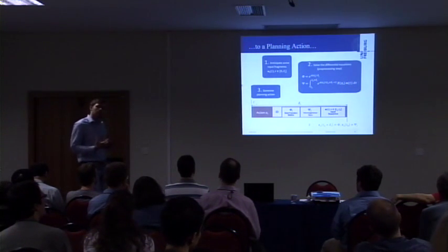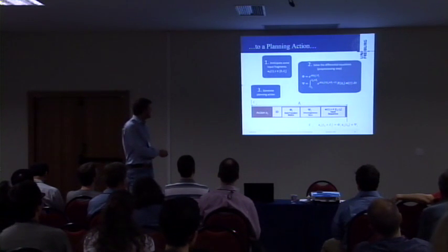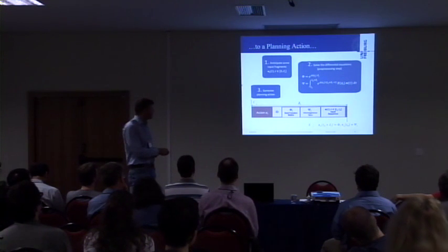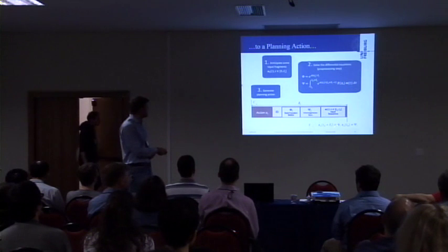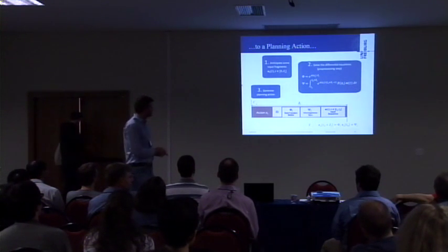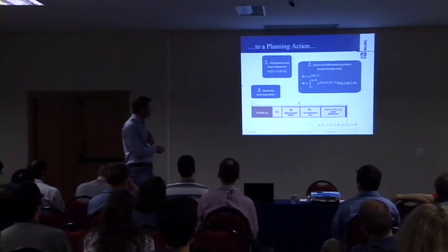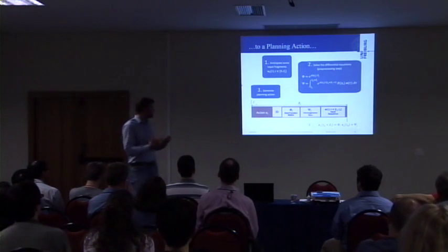The planner is now able to predict the future numerical state just by the evaluation of this equation. So we are in a current state with a current position, a current velocity, for instance, and we know the future numerical state just by the multiplication of the current numerical state with the state transition matrix, and with the addition of the inhomogeneous term.